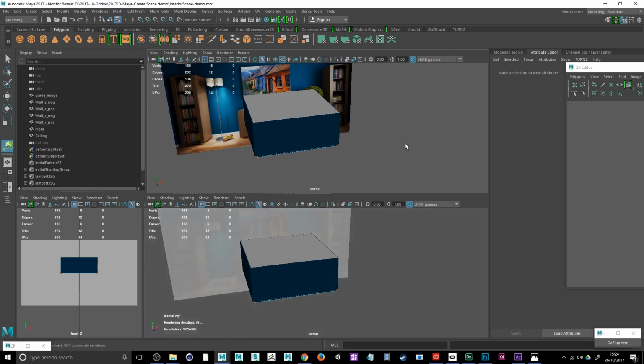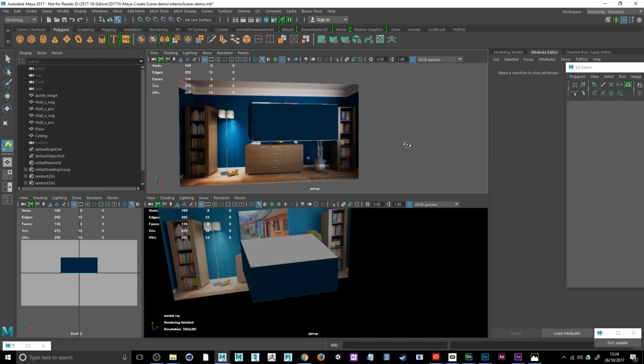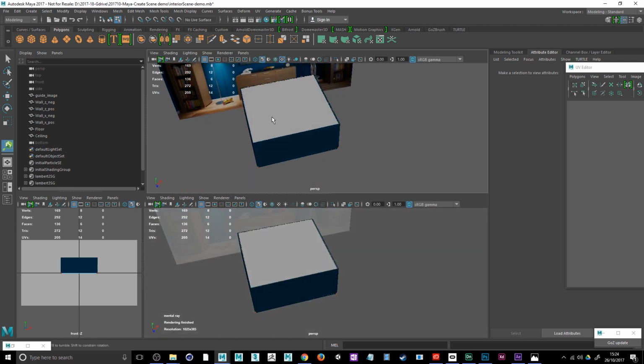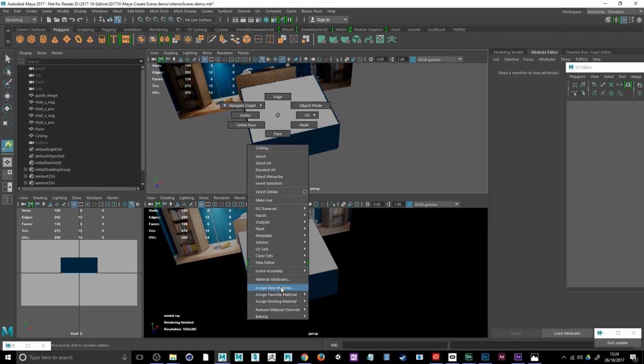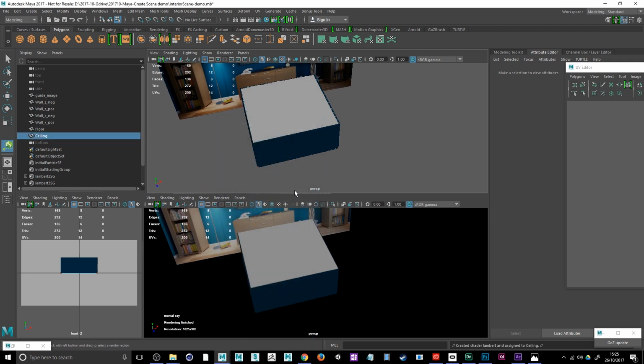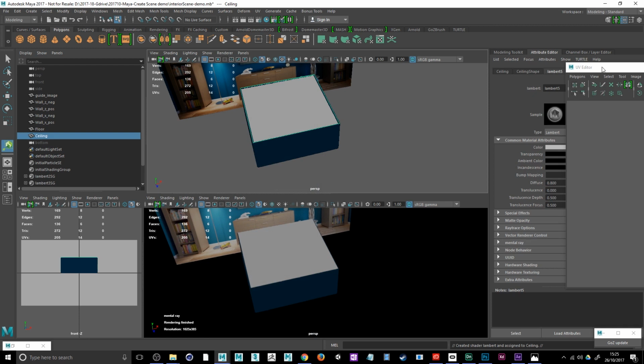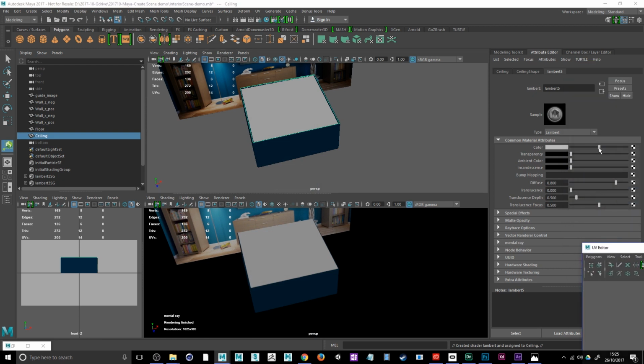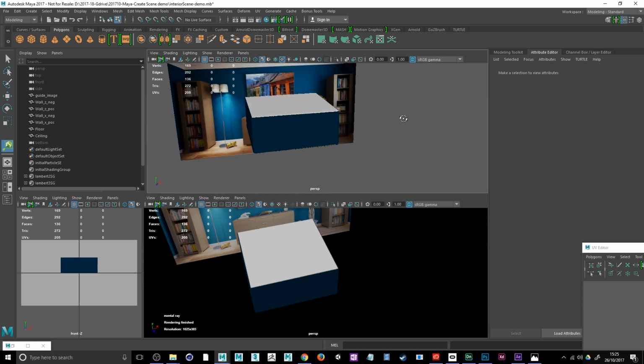So that's starting to set this up, and I think the last thing, I'll just check out the ceiling. The ceiling is plain white, so that's going to be a really easy one for me. Assign new material. I'm going to assume it's matte like the other paint, and I'm going to just bring that up to a white, and call that ceiling on the texture there.